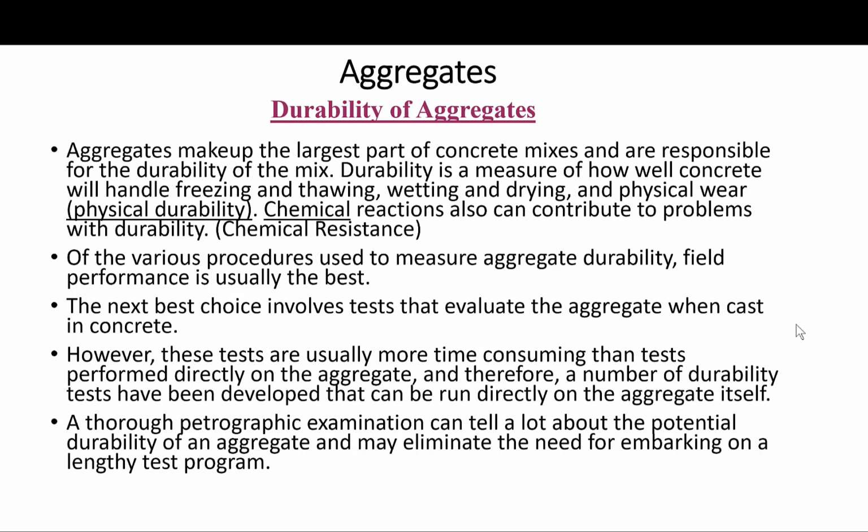A thorough petrographic examination can tell a lot about potential durability of an aggregate and may eliminate the need for embarking on a lengthy test program. So that is something to keep in mind. I know it's a specialty subject, a specialty skill, but it goes a long way in identifying potential problems with aggregate.